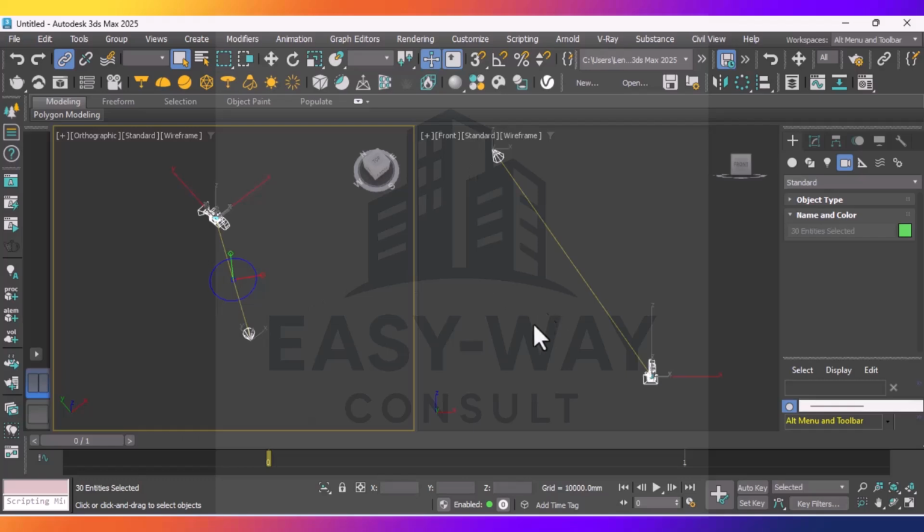So when you have imported it, you will delete this. There's something I forgot. In 3D Max it is very advisable, if you have cars, trees, flowers in your 3D model, maybe the one you brought from either ArchiCAD or this, to delete all those things, because they won't look as realistic as the ones from your Vray.